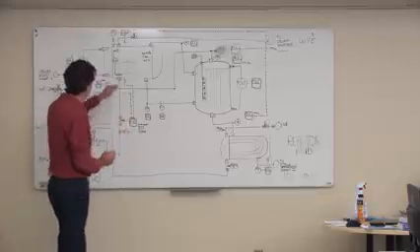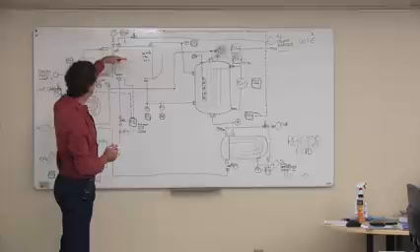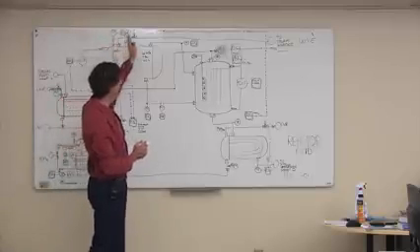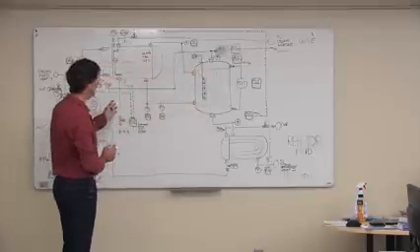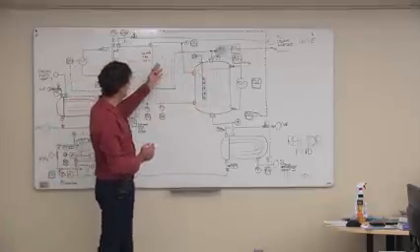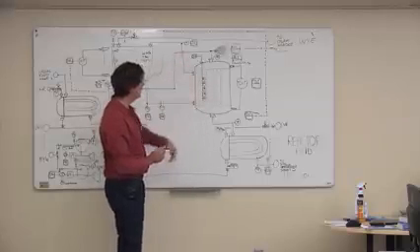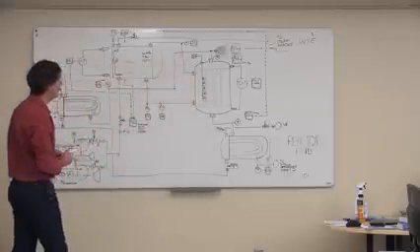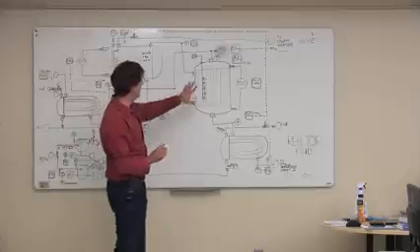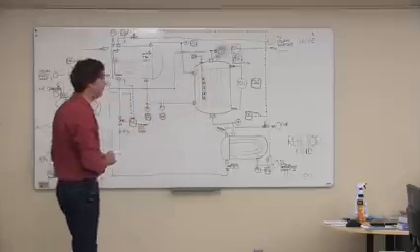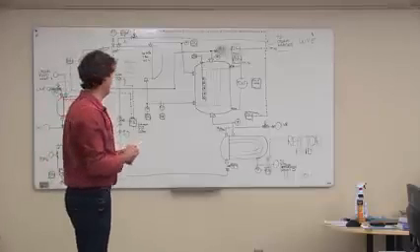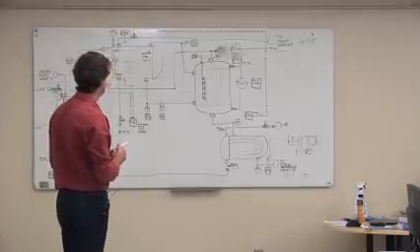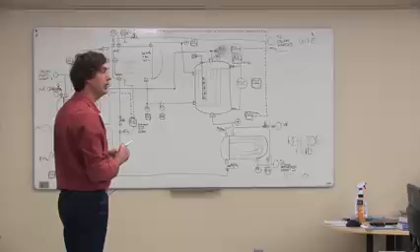If we fail it open, then we might potentially create some serious hazards here, because we could potentially flood the steam header, and that's going to create some serious problems. If we fail it closed, then we could potentially lose water into the reactor, and we could potentially damage the catalyst at some point in time. I don't think there's a right or wrong answer here. Either way, we are in deep trouble.